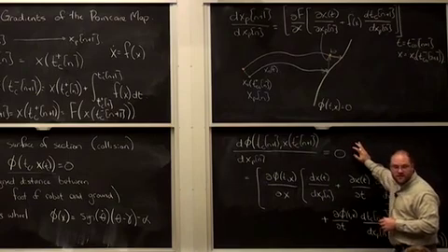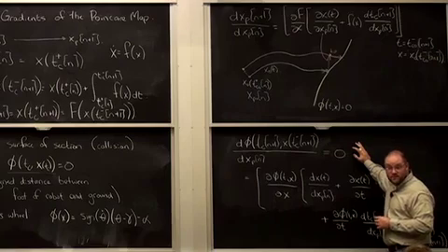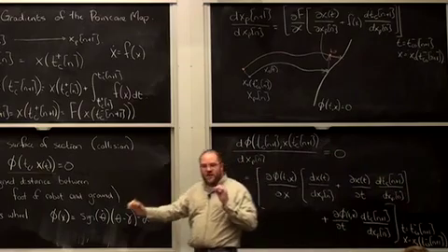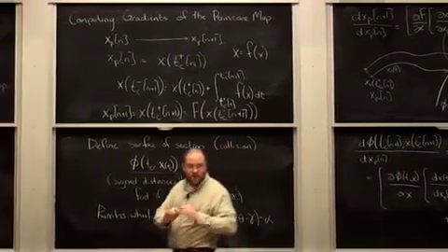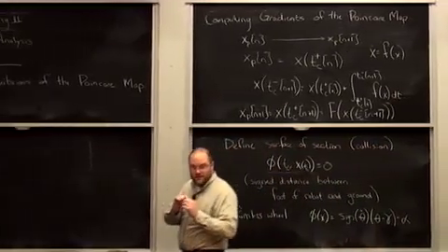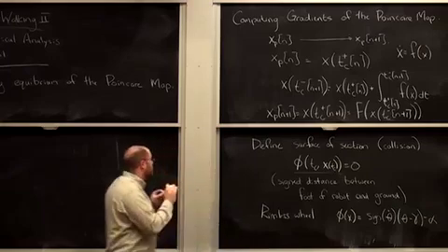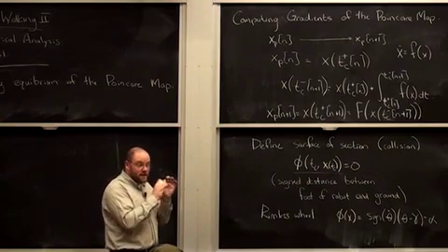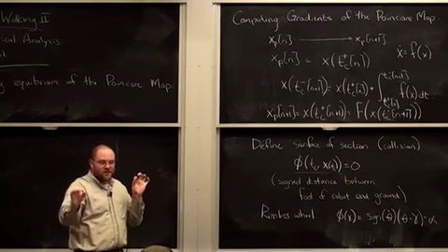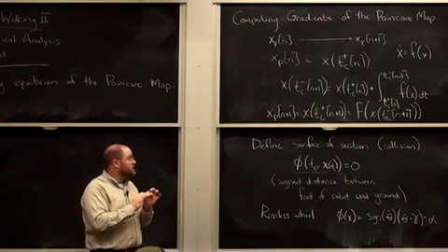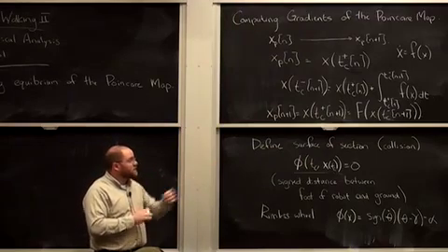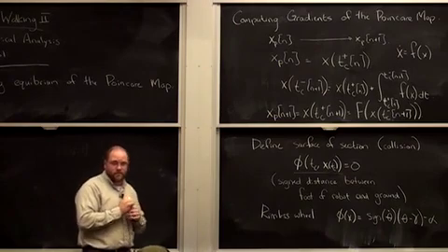That's all you need to use all those methods we did before. So if I wanted to now optimize the trajectory of my periodic system, if I had my dynamics, now we're back. I did this just in the simple case of f of x, but if I had f of x comma u, and I wanted to optimize u in order to do something good on the Poincare map, minimize some cost function, I can take the gradients, I can do my optimization.